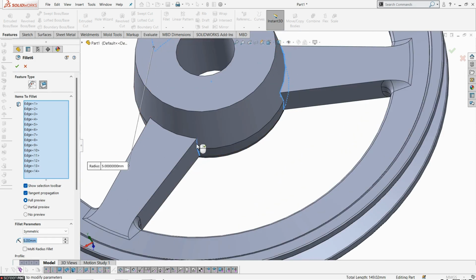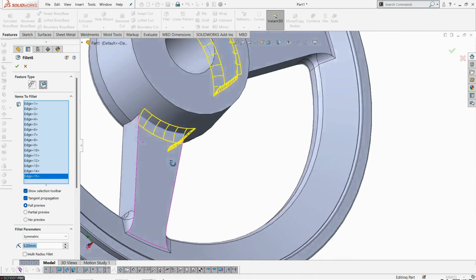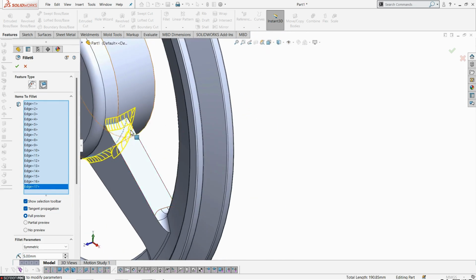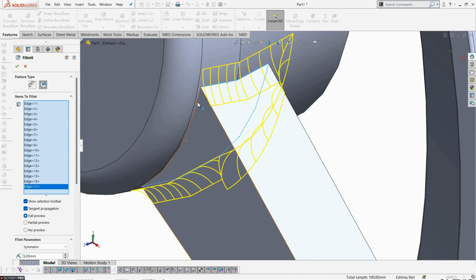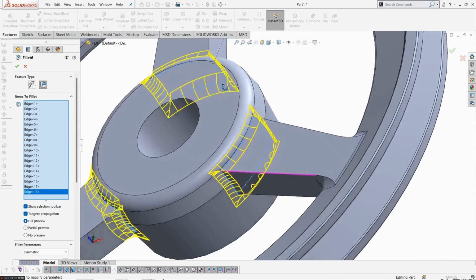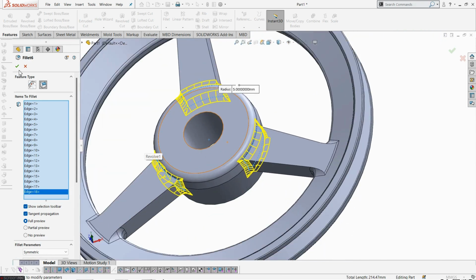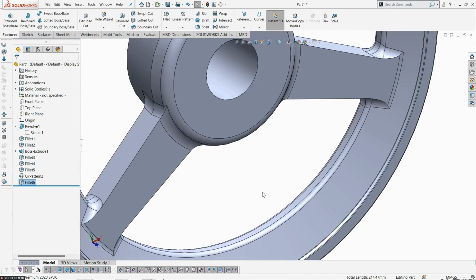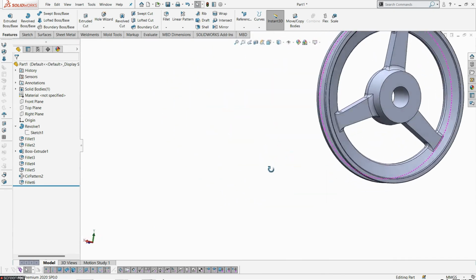Solid body. Same kind of fillet radius, 5 mm. Okay. Once it is connected within each other, we can easily make that solid formation. Now we are going to make a simple solid formation and pocket formation in these conditions.